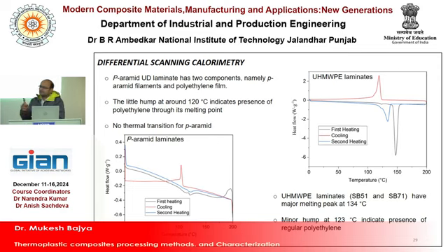First you will test your material behavior, what the material behavior will be with respect to the temperature. That material behavior you can test from differential scanning calorimetry. From it you can see the melting point and melting behavior of that material, and from that you can choose the temperature. Otherwise you can also reduce the number of optimization cycles if you have basic characterization knowledge.